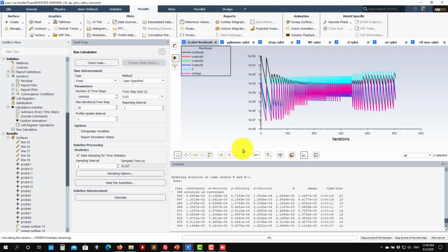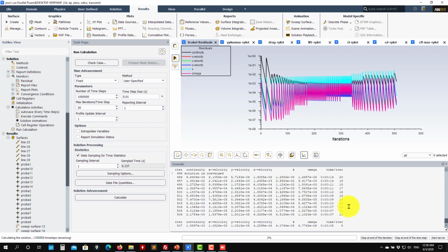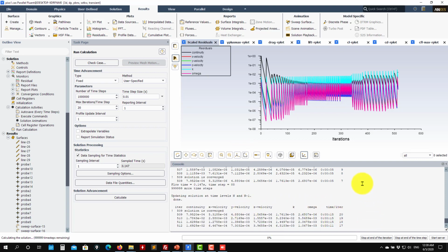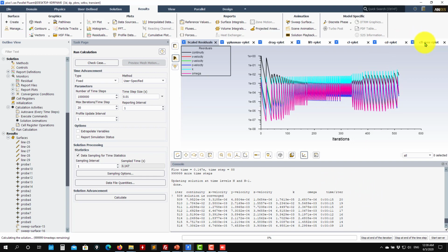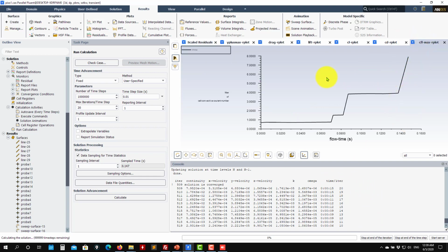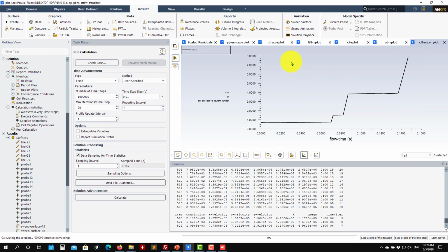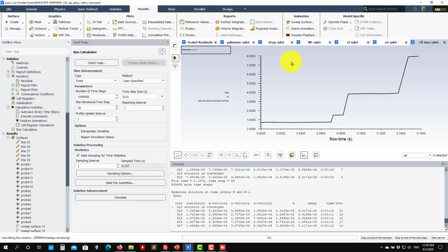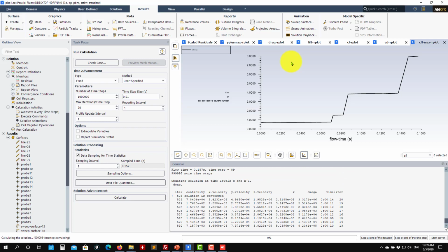We see a jump in the residuals, but also you will see that it will take longer to iterate. Okay, or 13 iterations. Your CFL is becoming 8, something about 8. So the methods implemented in Fluent, they are implicit.